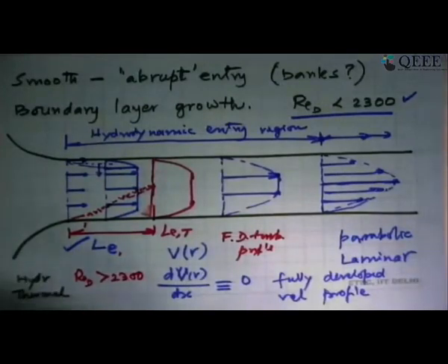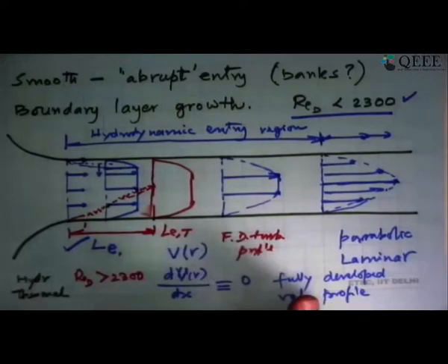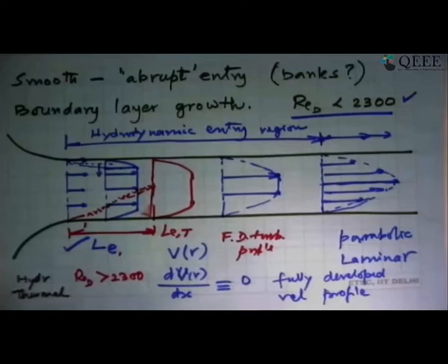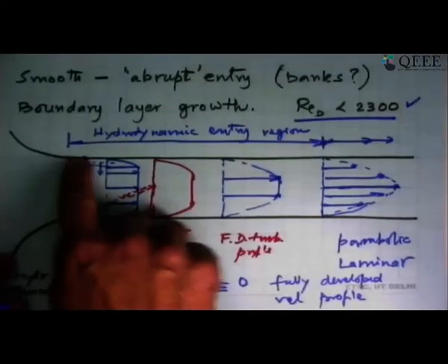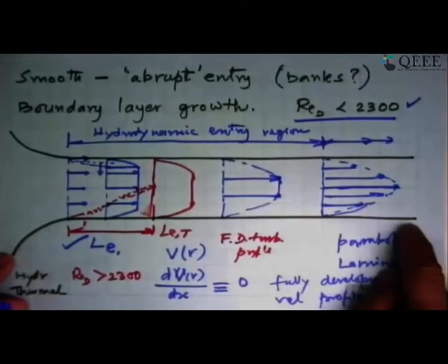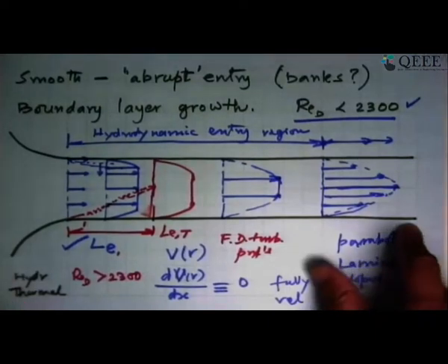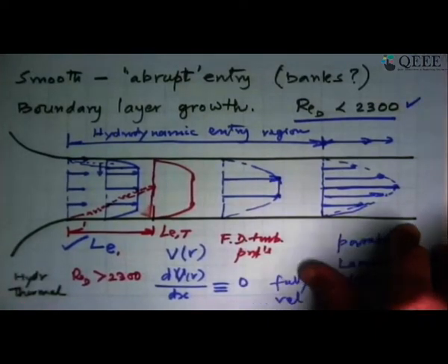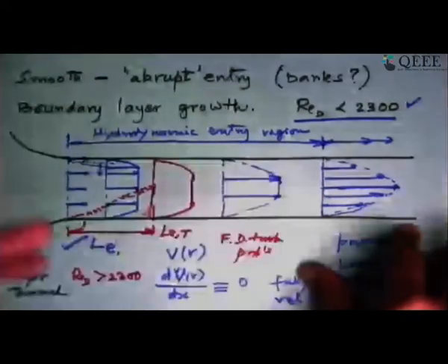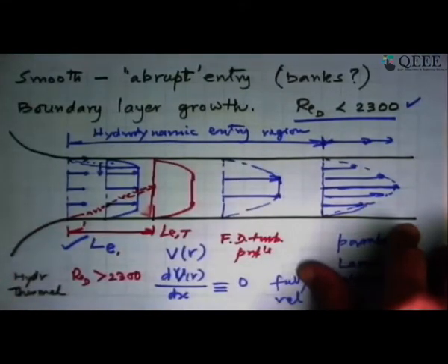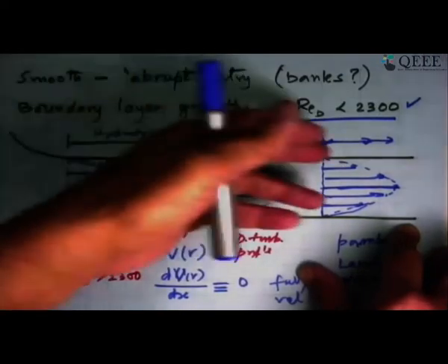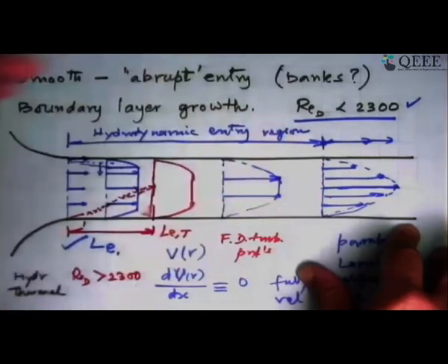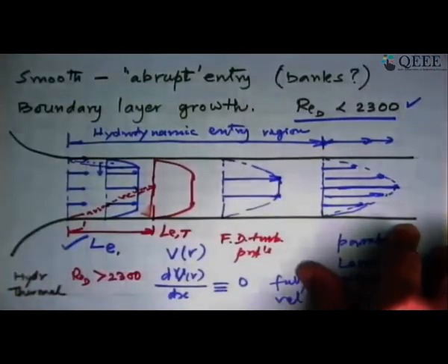The second thing is now we impose a heat transfer condition on this tube. And like we had looked at the flat plate, we have two options. One, the wall is at constant temperature. An example is a thermal power plant condenser, where inside you have cooling water flowing, and outside steam is condensing. Steam condensing means that its temperature and pressure are going to remain the same. So the temperature is constant. The wall being a very good conductor, you can say that the temperature of the wall is almost constant. That is an isothermal wall for the case of a tube.